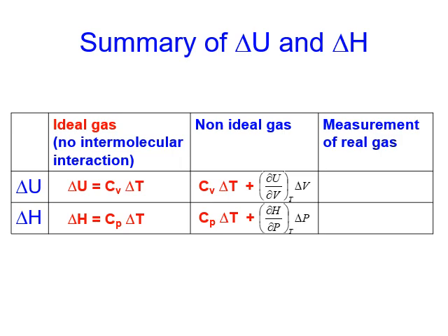So how do we measure in the lab? We measure when we choose volume constant for internal energy. When volume is constant, the second term is 0, and therefore delta U must be Cv delta T. And for enthalpy, we measure under constant pressure because this term becomes 0, so it's just Cp delta T.